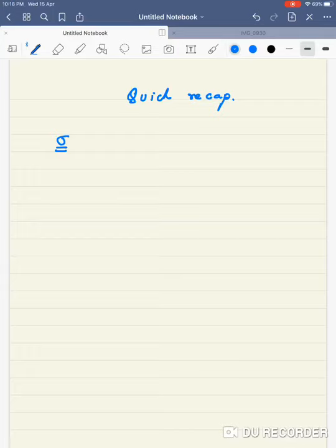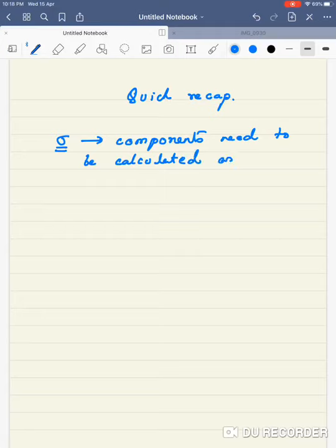Even though the stress tensor exists as an abstract quantity, in order to evaluate it numerically you need to decide which reference frame you will be using, because the components of the stress tensor need to be calculated as per the current orientation.